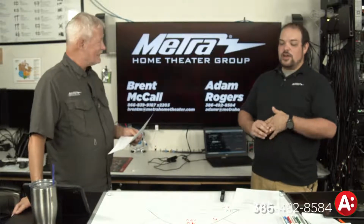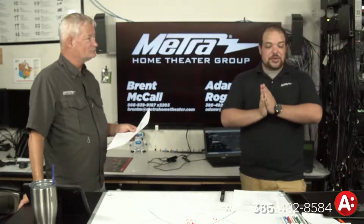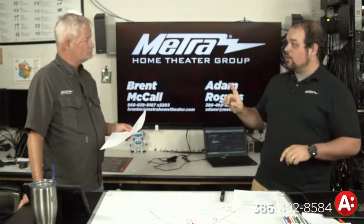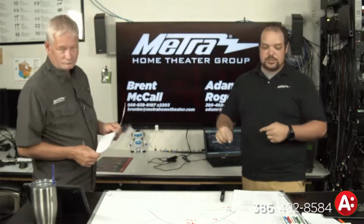Exactly. We're going to talk about the HDBaseT stuff because it's really interesting. That's how it gets that much power across: it's using 4 pairs across the category wire, and it's still able to get that high amount of data transferred all the way across, with differential power.